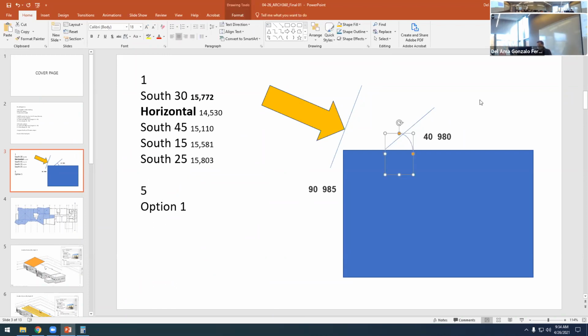So this result makes us think of, why can't we integrate PV panels on the facade, on the vertical south facade? That's an interesting option for winter. Because in winter, the production on a vertical facade is higher than the production on the optimum angle, which is 40.